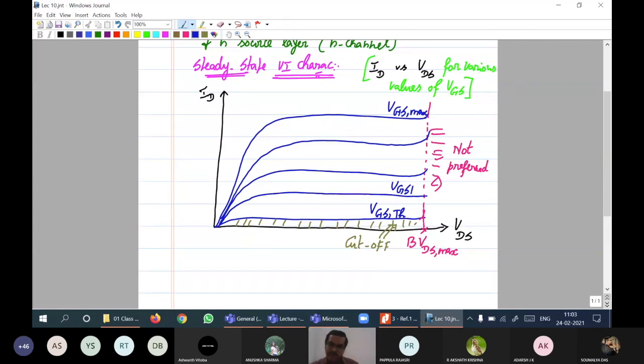Okay, no snakes in between. So when you draw on paper or on a board, due to friction, the line will be straight. Whereas here it's somewhat up and down. And in a transistor, this was not the case. If you can recollect, this curve was not flat. The horizontal line that I am drawing, the ID value remains constant here. That is the meaning. For a particular value of VGS, ID value is going to be constant in a power MOSFET. Whereas in a power BJT, it was not constant. It was keeping on rising.